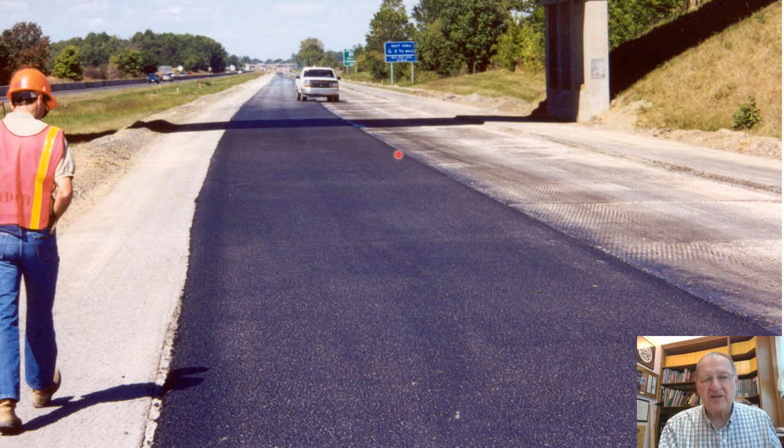So here we are on an interstate highway. The project called for milling the existing overlay down to the old concrete and placing an intermediate layer and a surface layer on top of it. They've been placing this 19mm intermediate layer that I just showed you the picture of the gradation of. They've been putting 14 passes of the roller on, trying to get density. They sort of are getting density, but it's kind of marginal. So sometimes it passes, sometimes it fails.